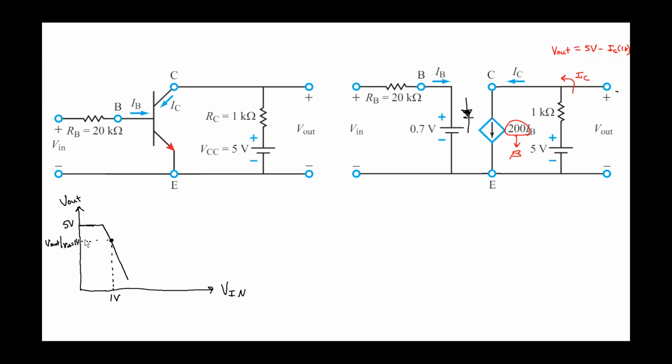The question then challenges you to work your way backwards and consider when this graph hits 0. At some point, there's going to be so much current flowing in here, so much of a voltage drop across this resistor, that Vout will hit 0. And we can't go below 0 because we only have this single-sided voltage supply. So for the rest of that graph, we're at 0 volts.